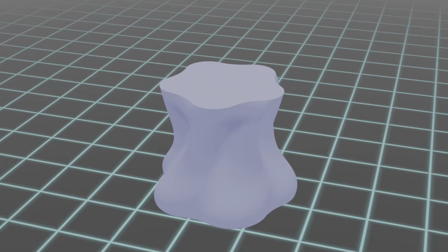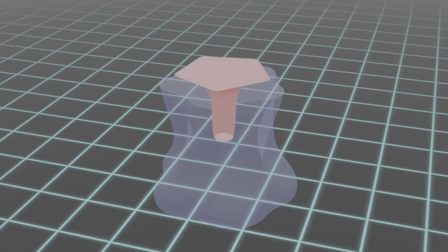After this point we have a solid, and it's basically a bunch of Boolean cut operations. I want to break up the flat end of this surface, so to do that I generate an internal kind of void using the same principle as offsetting shapes, but this time I use a negative offset, so it's a smaller subshape, so it cuts out this kind of nice curved profile.